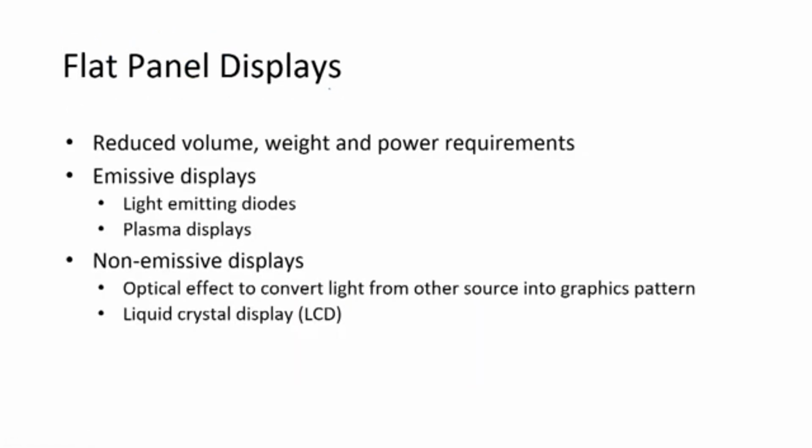Then recently we are using flat panel displays. These flat panel displays have reduced volume, their weight is also reduced, and certainly they save a lot of power. Instead of handling a very big device, that is a CRT device, we are using very thin display devices, and these are emissive displays, that is the plasma displays and LED displays. There are certain non-emissive displays also being used, and these are the LCD, that is the liquid crystal display.